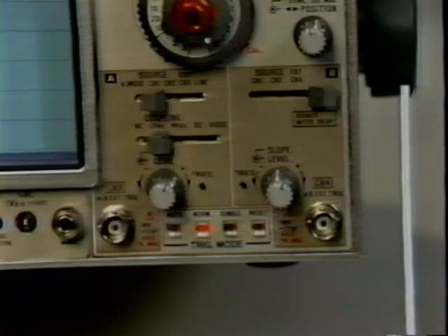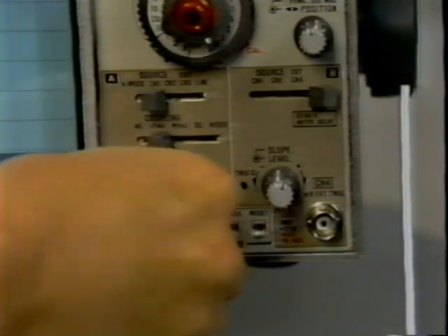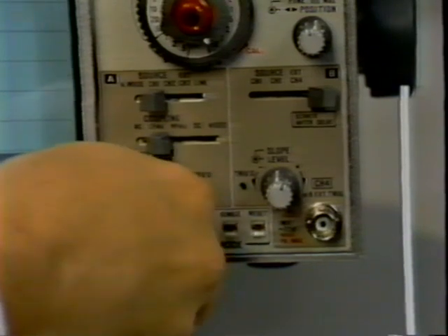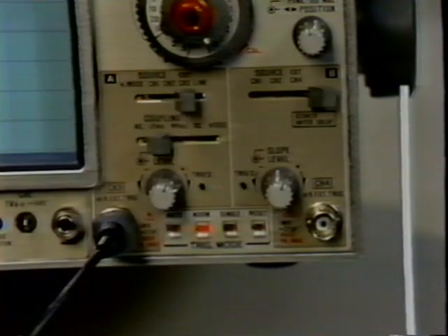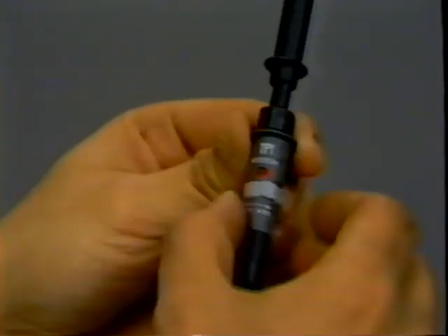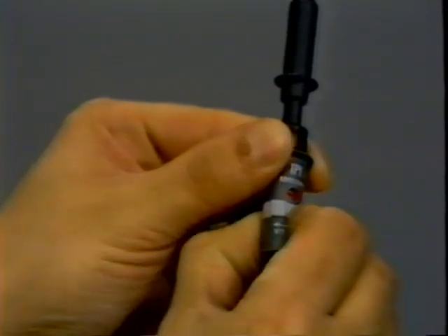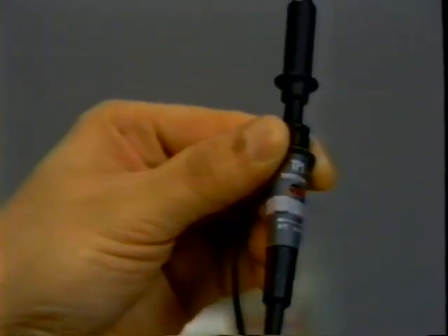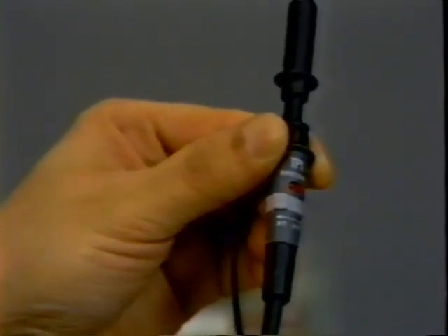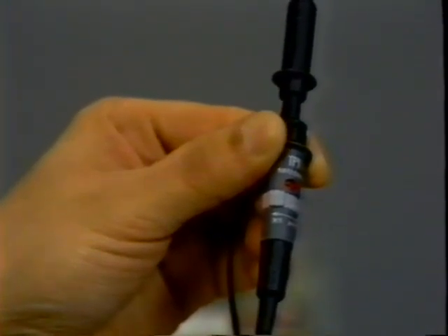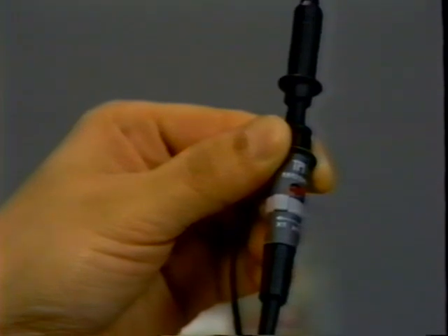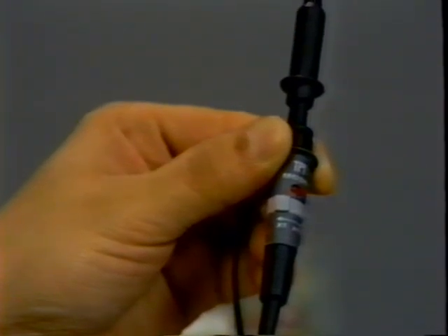This allows us to observe one or more signals in relationship to the timing of a third. To set up external sync, connect a probe to the jack marked sync source on the front of the scope. Then select the external option on the sync source control. Always use the ×1 setting on the probe used for sync unless the input has an amplitude of 20 volts or more. Since the trigger circuitry detects changes in signal level, the greater the range that we give it, the more easily synchronization can occur.